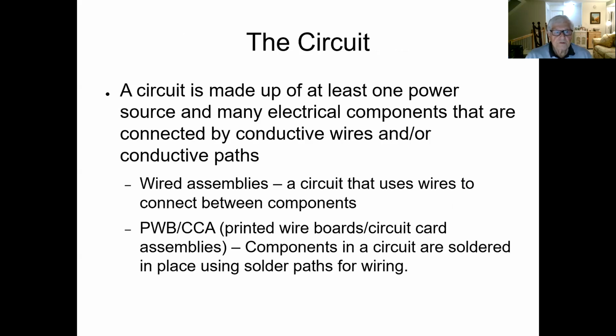So now we get to the first step, which is we've got to create a circuit. Okay, a circuit made up of at least a power element and some electrical components that are wired together, or conductively together. We can use wired assemblies, which means we're just taking individual components and using wires to connect everything up. But of course, the more standard way is to use a PWB, which we call a printed wiring board.